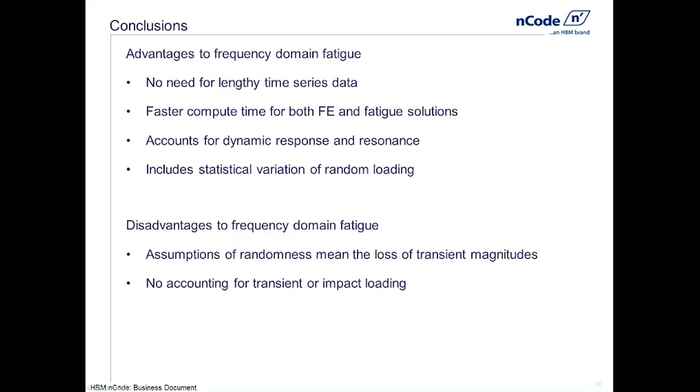I've seen a number of people do this with success, looking at the transient stuff using direct transients or modal transients in the time domain, and then looking at the fatigue damage contribution from the other more stationary loading histories using vibration fatigue.